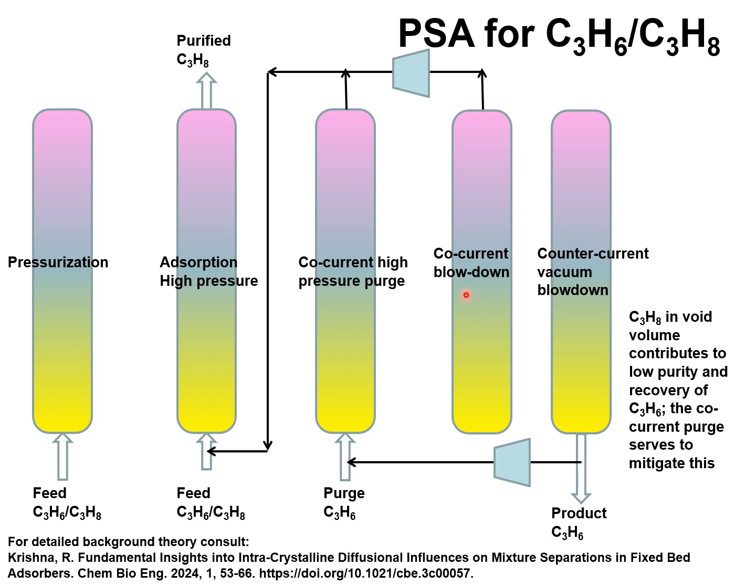There's considerable effort in the development of metal organic frameworks and ZIFs for separations of propene-propane mixtures. Many of these adsorbents are selective to propene, and therefore the desired product is only recoverable in the final countercurrent vacuum blowdown step.